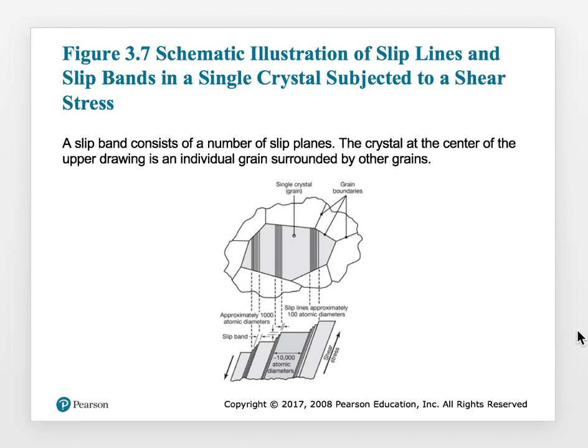And when do you stop the deformation? You stop the deformation such that you make enough deformation such that those grains will start deforming, and then they will go and stop. They will get stopped by the next surrounding grain. So it can only move a certain distance. So it can only move a total of say 5, 10, 15, 20% strain. If you go beyond that, it is going to make the component fail. You do not want to make the component fail in a manufacturing process. I hope you are understanding what I'm trying to say here.